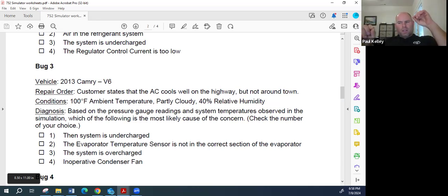So at that point, and by the way, that could be out of spec. Let's make it a half a volt. If I'm dropping a half a volt on a connection of the battery, that's out of spec. But is dropping a half a volt gonna make the cart not move? No. So in my mind, the way I've been trained, the way I've come up, and the way that I've understood how the business works, I understand what the customer wants, and I understand what the business wants too, but ultimately they brought it to me to diagnose why it won't move.